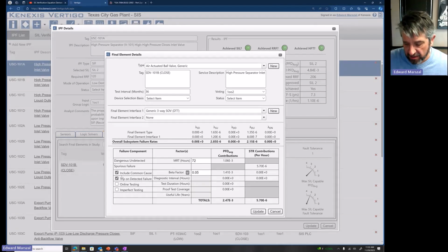The fact that an IPL, whether it's a safety instrumented function or not, is used in multiple scenarios does not change the frequency of any individual LOPA scenario, because all of those LOPA scenarios are independent of each other, because they begin with an initiating event, which is an infinitely small point in time.